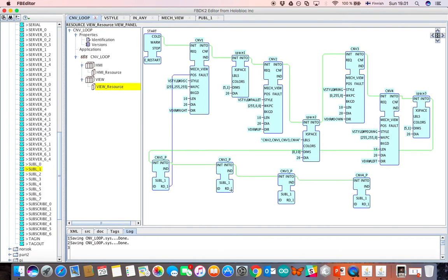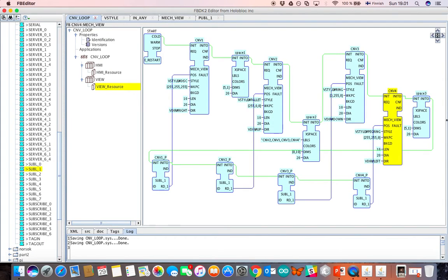So now I just have to interconnect positions here for CNV2, checking the indexes that I am going in the correct order. Okay, let me just drag and drop it here and rearrange it, RD, and so that's it. I have connected all the publisher blocks to the corresponding subscriber blocks by having unique and matching names of the blocks, Publ and Subl_1.